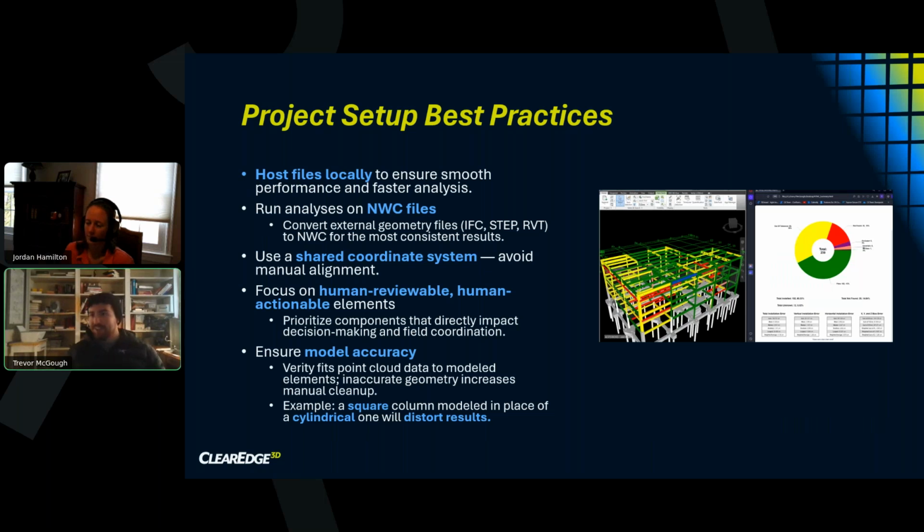and not saying that ever happens on a construction site, and all our Revit models are absolutely perfect and representative of real life, but if the case does happen, one of the big ones we see is, for example, a square column that was actually scanned as a cylinder. That's when we can start getting issues with fitments and stuff like that. So again, we do want to make sure that whatever we are trying to analyze against the point cloud is representative, or roughly has a higher LOD, so that way Verity can actually get a good fit against the cloud. But everyone's BIMs are perfect, and we never have to deal with that.